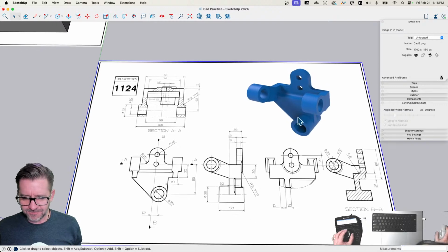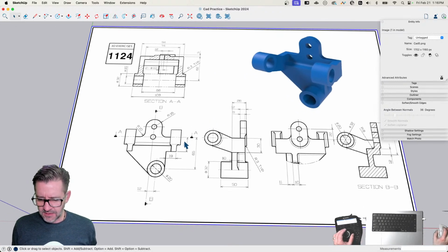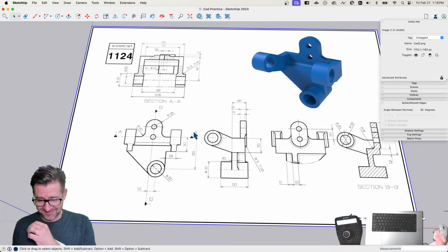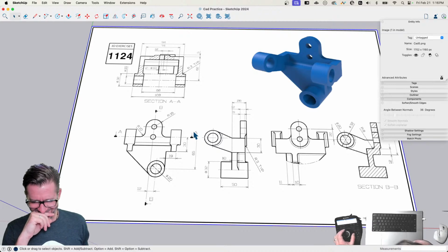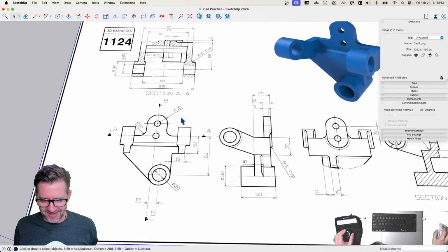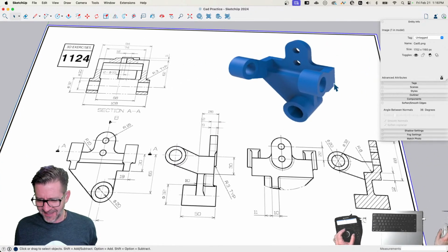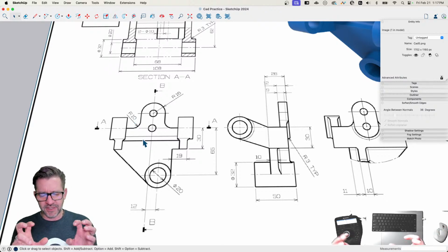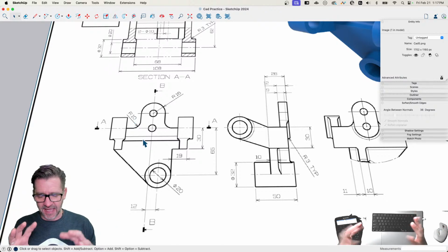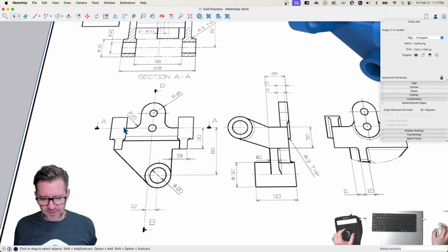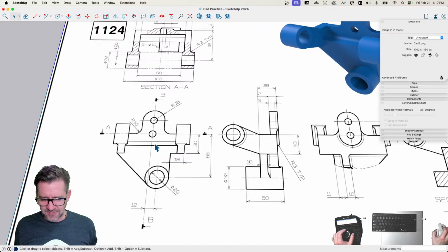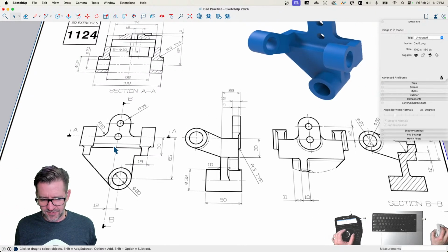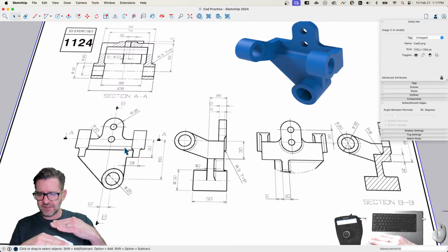So again, breaking this down. This is a model that I look at and I say, there is no function for this. This is somebody who's just trying to show off with their CAD design. Could be. All right, it's not that complicated actually. It's holding some kind of a shaft this way and then something this way and it gets bolted together this way. So I would design, probably this would be my base plate. This is a concept that helps me anchor the model. I would probably start with this shape right here. And then it looks like this piece right here steps up. See that? So I would probably start with those two pieces.